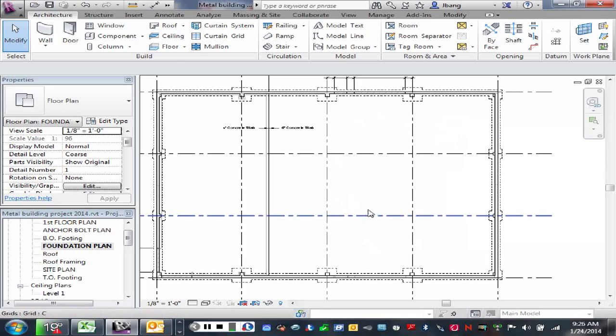So in my case here, I have a door here and a door here. So you want to put the floor drain under where a vehicle would sit in the building. It's a trench drain. Let's say you bring a truck in and it's going to sit in the shop over this floor drain, and anything that drips off of or falls off of the truck ends up in the floor drain. So we're going to put it directly under the path of where a vehicle would drive into the building.